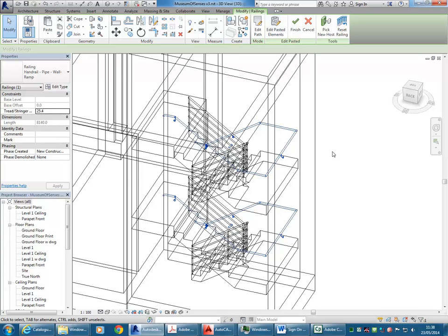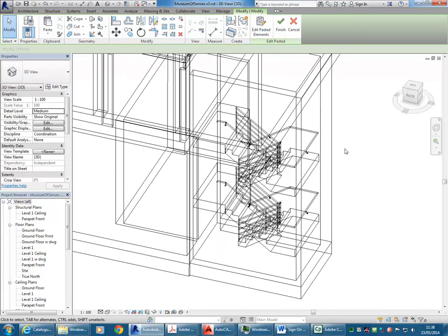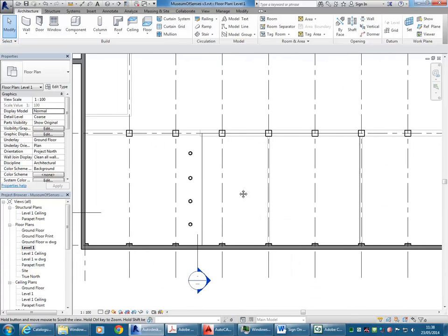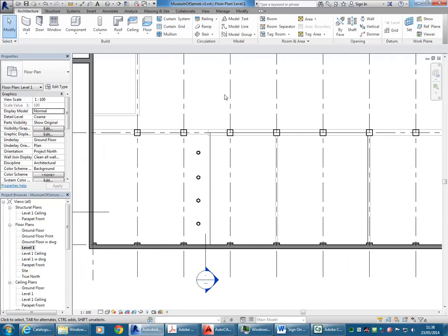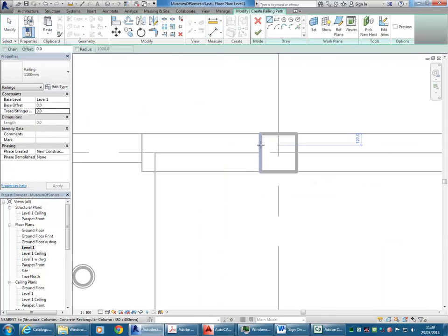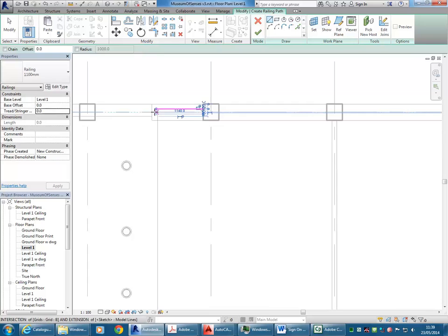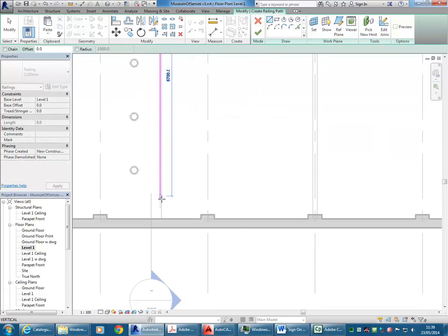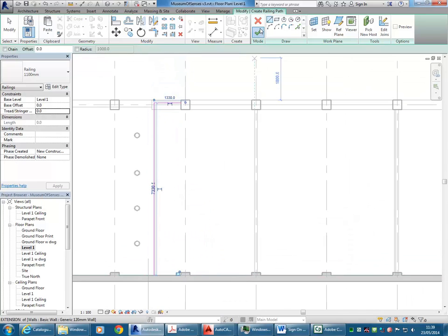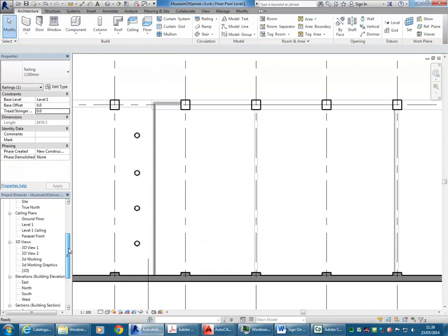So, railings, you can see they're separate objects, and maybe I can't help myself, it's a fun thing because I did want to show this to you today. I just want to draw one by itself. You've got the railing tool, even easier to use than stairs. I'm just going to use sketch path, and I'm going to draw a line. That's the path for my railing. I'll finish that, and then in my 3D view,